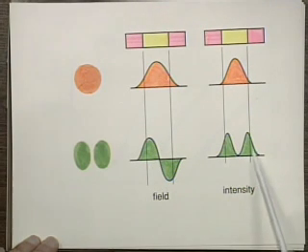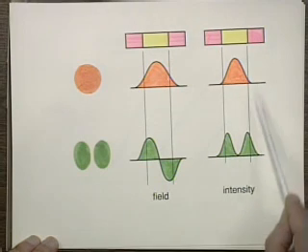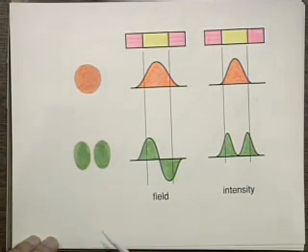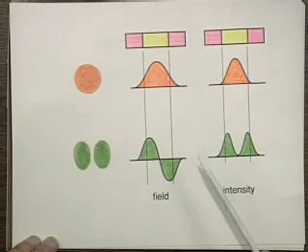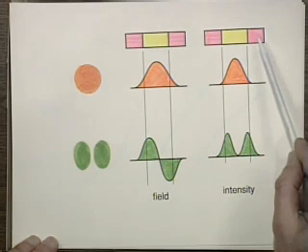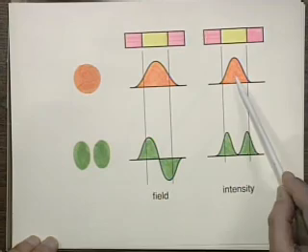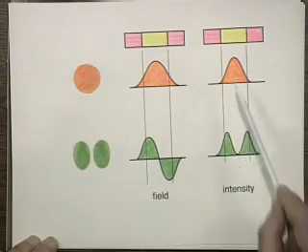And what you see here is that the size of this higher order mode is bigger than the lowest order mode, and more of it will propagate in the cladding than in the core. So in terms of propagation constant, or how fast they propagate, this one propagates more in the cladding than this one, and since the index is smaller in the cladding than in the core, then this one will go faster than this one.